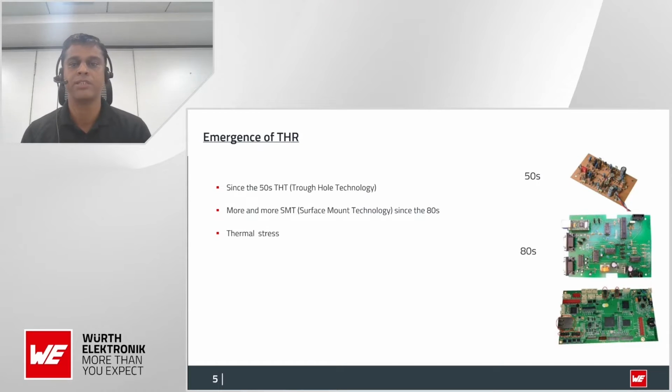What exactly does that mean? When you have a PCB with a combination of through-hole components as well as surface-mount components, first we assemble the surface-mount components and then the through-hole components, because surface-mount components are assembled at a temperature of around 265 to 285 degrees. When it comes to wave soldering, the component gets assembled at around 235 degrees. Since we have this huge temperature difference, we have to assemble the surface-mount components first and then go for the through-hole components.